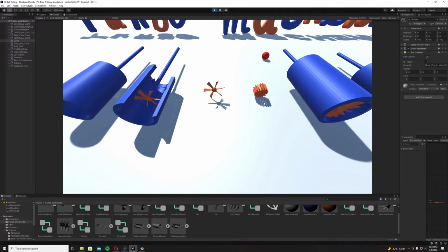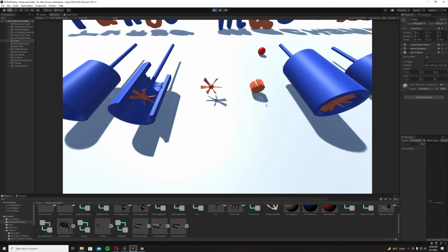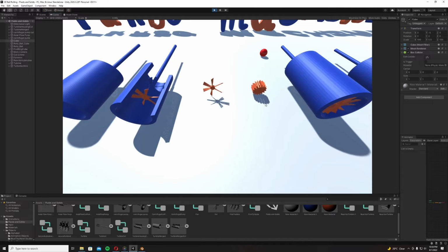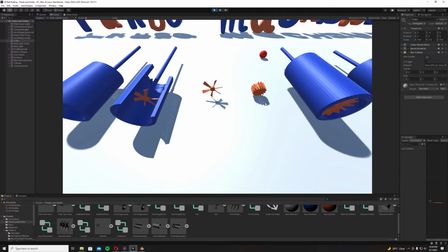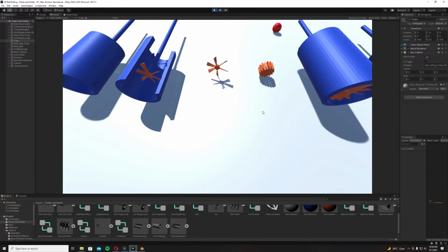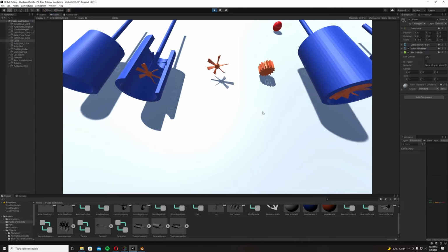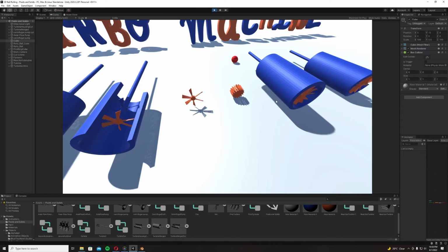Fans increase the fluid's velocity, but they have very minimal effect on its actual pressure and density. So when performing calculations, the fluid is often considered incompressible. With the low pressure change from interacting with the fan, most fans utilize lighter weight materials, since it's easier to spin a lightweight material and it won't be damaged due to the small pressure gradient that occurs within the system. Some industrial applications of fans include high temperature circulation of air, saturated air exhaustion, and airborne dust extraction.